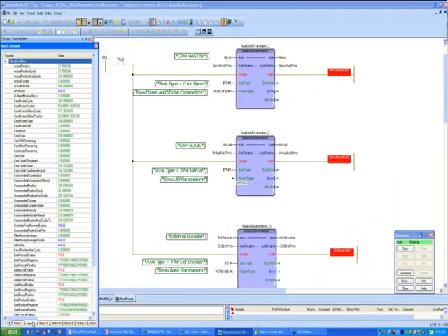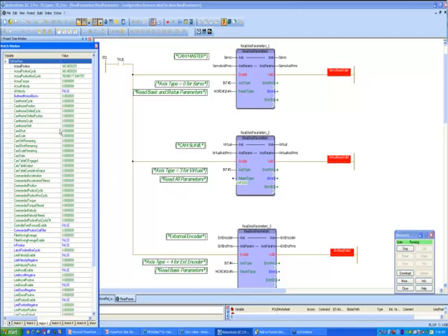For my virtual axis, which is a slave or CAM slave, you can see here that it has all the relevant position parameters and all command. Since this is a CAM axis, it does have all the CAM parameters too that are getting updated every scan that this is being read, since it's enabled throughout. And lastly, we have the external encoder, and you can see for an external encoder, since I'm reading only the basic parameters, only a few parameters are getting updated here.